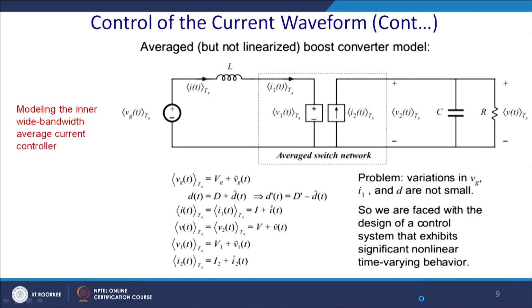Now, we can go for the small signal analysis to analyze the stability of this PWM boost control converter. Now, it is an average model. So, any phenomena less than 10% of its switching frequency can be captured here, and this is called the small signal model. What is the essential part of the small signal model?